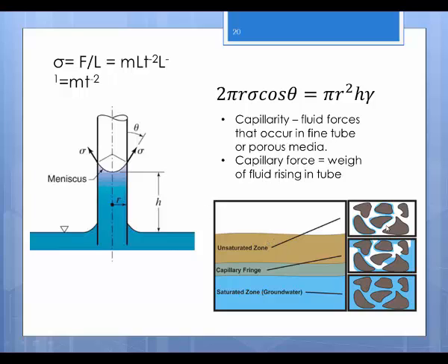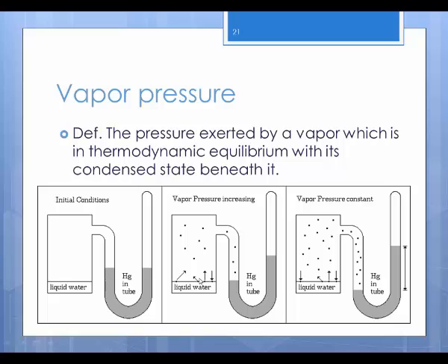The unsaturated zone is a little different, because that is just water that remains after draining. This is saying it's actually pulling water from the main aquifer region into this other area. So if this is anywhere significant, it's going to affect some kind of groundwater balance in terms of how much water you really have available to pump or how fast groundwater is going to move. So understanding capillary forces is important. Surface tension comes in more than you might really think.